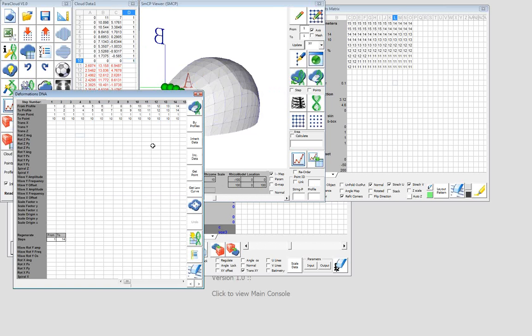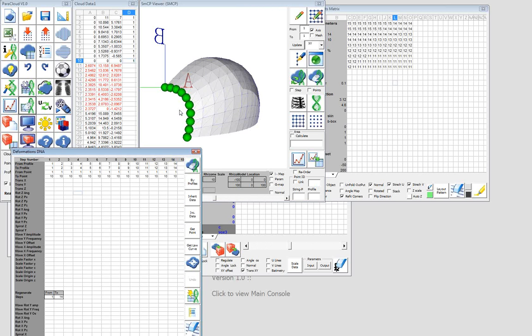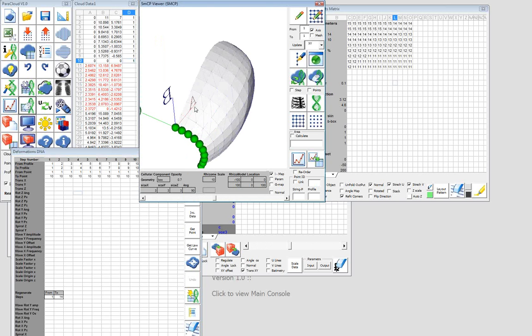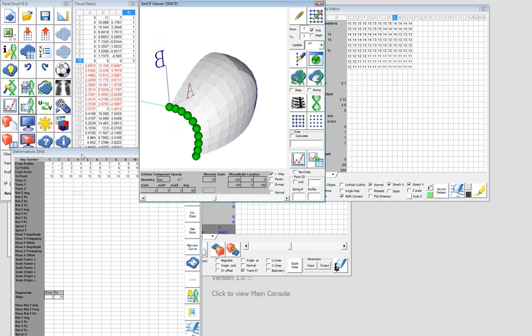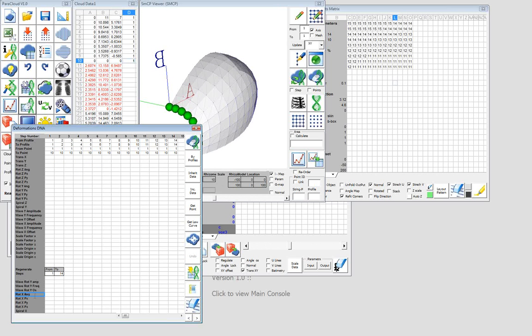So what I'll do here, I'm going to use a rotation about the z-axis. The z-axis is, let's do actually on the x-axis. We'll do rotations about the column A, which is the x-axis of our geometry. And what we need for that is to set rotation angle for the x parameter. So I'm going to use two values. The first profile, I want it to stay in place. The second profile, I want it to rotate, let's say, by 10 degrees.